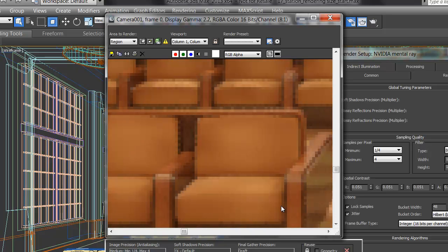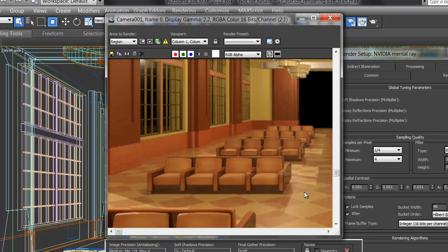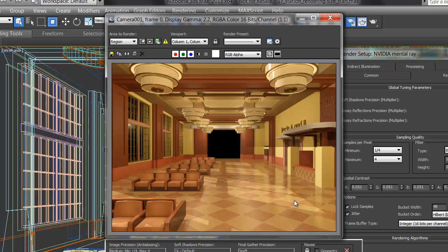An image produced by 3ds Max is composed of pixels, and these are in a grid, as you can see. Therefore, diagonal lines are blurred or interpolated between horizontal and vertical in different colors. They are anti-aliased. Aliasing, then, is stair-stepping artifacts that we see in a rendering. So I'm going to kick up my anti-aliasing a little bit, because I'm going to need it when I start doing a larger render. And it'll really be apparent in places like the tile floor here.